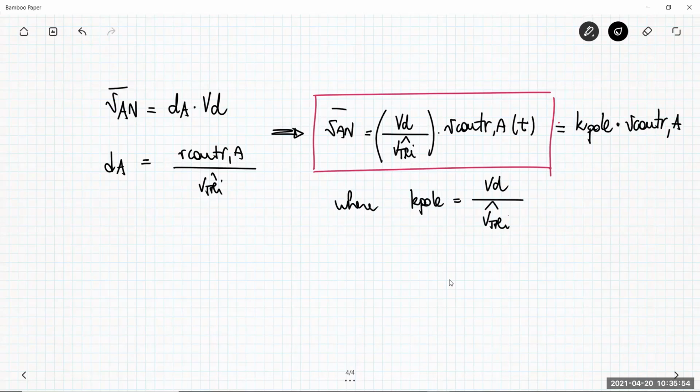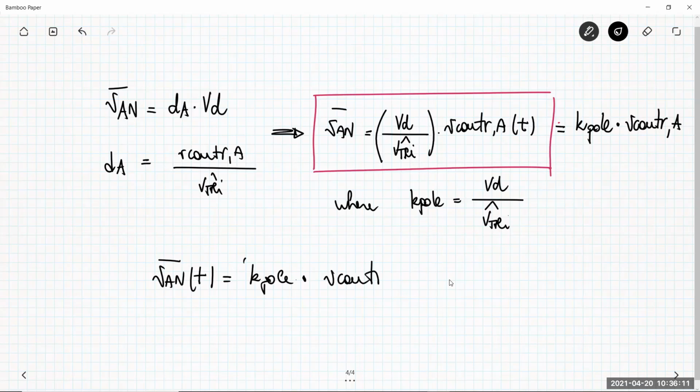In these terms, you can see that here you have an amplifier, because the average value of the output is simply a constant term multiplied by the input. So you can say that from the control signal to the output average quantity, you have a sort of amplifier.